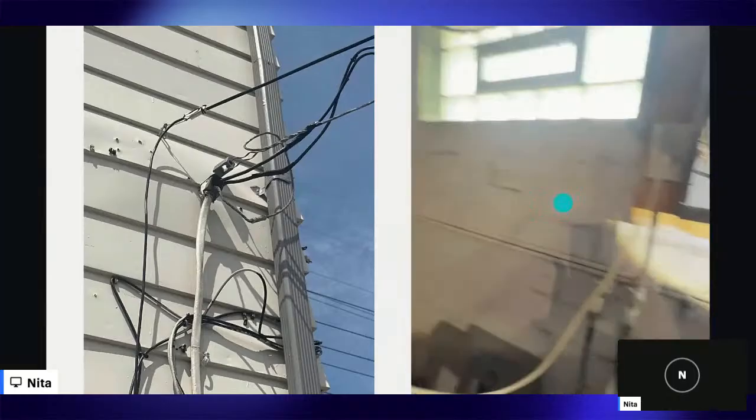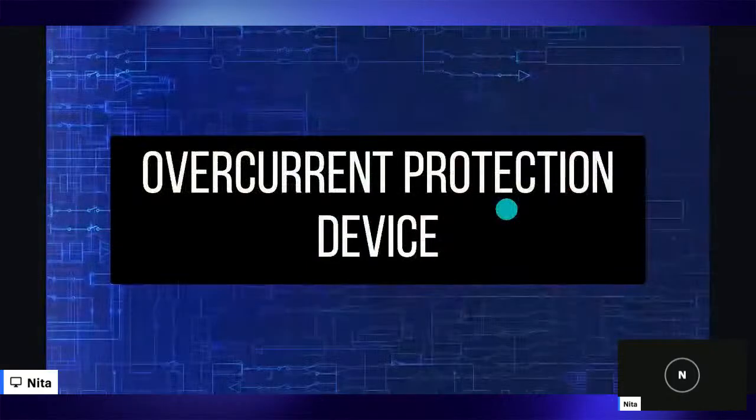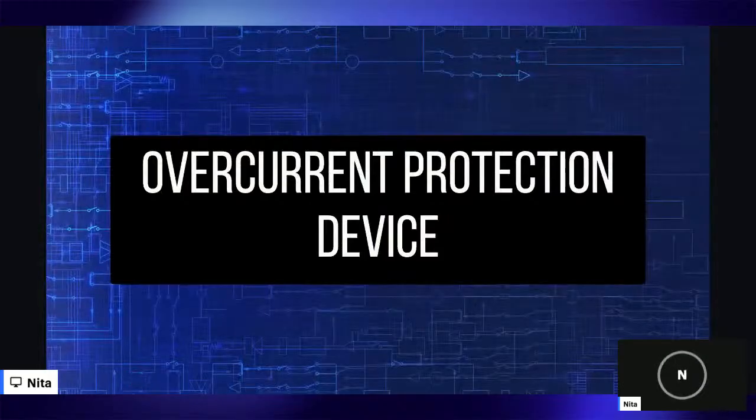So the GEC is going back to the GE. So at your equipment, you got EGC, which goes back to your grounding bar. At the grounding bar, you have your GEC, your grounding electrode conductor, which goes to your GE, the grounding electrode, or the ground bar. You see how that works? So we have a ground at our equipment. Remember we said that? Then we have our entire system that is then connected to the ground as well.